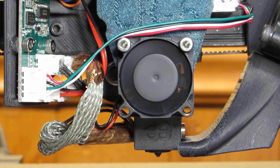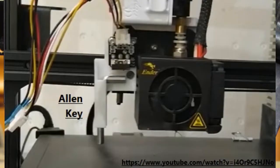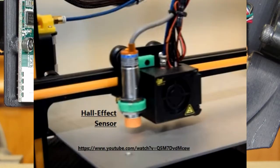In each case they represent a distance between the tip of the nozzle, where the filament's going to come out and lie on your print, on your model, and the tip of the probe, where the probe decides it has detected the bed. So the probe in automatic bed leveling systems, all probes, and there are many kinds of probes, are intended to tell Marlin Z equals 0 is now.